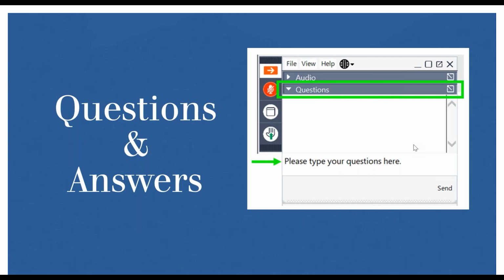Can we reuse the Dräger Tube for the next measurement if there's no discoloration? No, because the tip is broken, it has been exposed to the external environment. So the external substances might be trapped in the pre-layer or indicative layer. That may disrupt the chemical reaction and affect the discoloration. Therefore, the concentration might not be accurate when the tube is broken and reused. So it's advisable not to reuse, right, Agus? Yep.